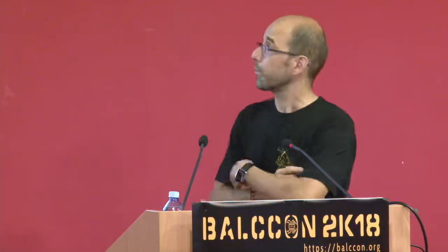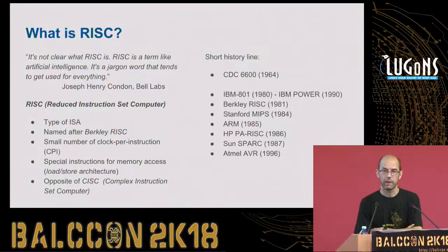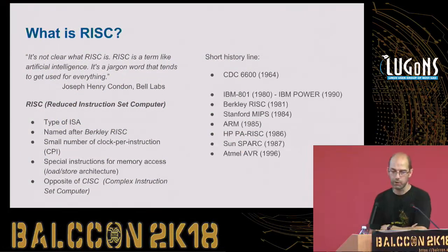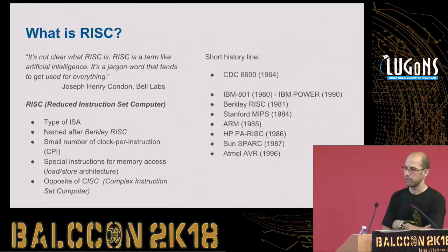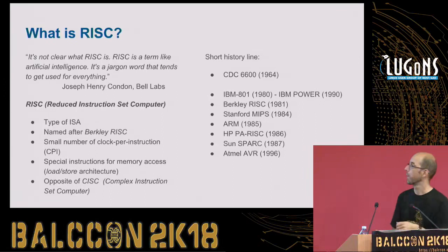So when the microprocessor came, they kept the logic of the minicomputers from the previous era. So complex instructions were the main thing, but these complex instructions take a lot of time to execute, and they are fairly unpleasant for modern parallelization techniques like pipelining.